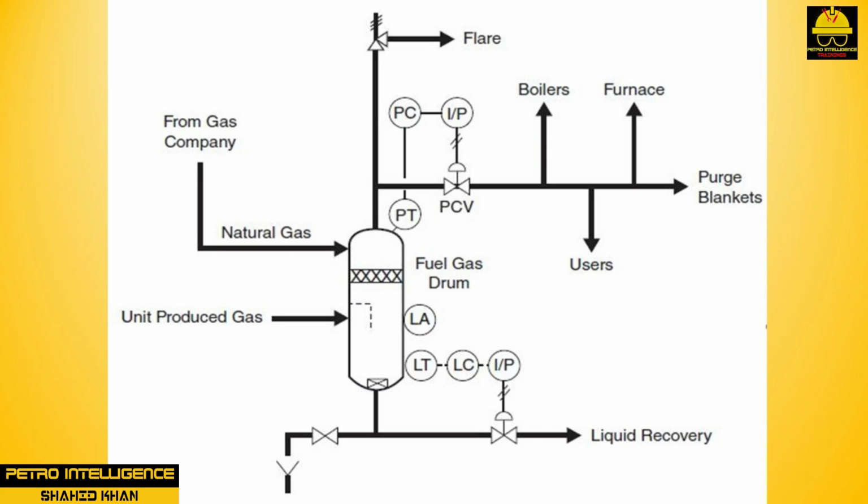Natural gas is used to supplement the fuel gas produced at a unit in order to meet furnace and boiler demands. Natural gas is also used as a purge medium in unit startup and shutdown. Fuel gas generally consists of plant-produced process gas that is augmented with purchased natural gas to satisfy the unit's energy demand. Fuel gas required is typically produced internally during normal unit operations.